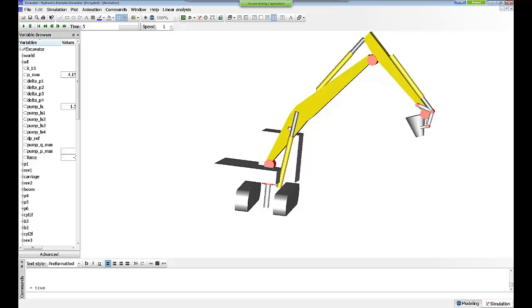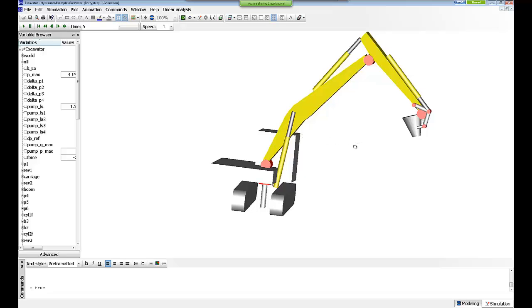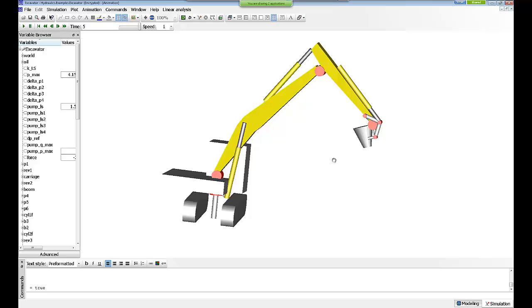But when you start rotating, you get an outward force due to the load out here, and that's going to pull it. So the dynamic forces are very different from the static ones. So it's a very powerful way of including the hydraulic system with a correct dynamic load situation by using the combination here with the multi-body dynamics library.